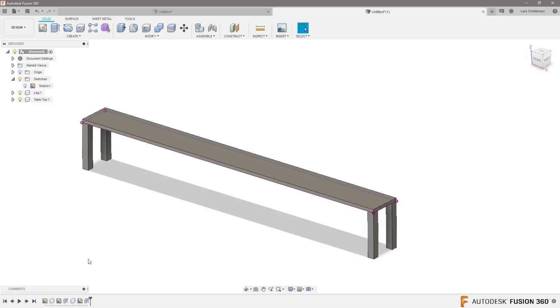But what I can do is hold down Control and select these 3, they all belong together. If I right click on them, you can create a group. And when you do that, they all get grouped together in here. You can hit the little plus sign, expand them, or hide them down like that. Same thing, I created these in an order. I created first the component, then the sketch and the extrusion. I can also select these 3 items, hold down Control, right click, and group those together. So that's one way that you can start ordering things together in this timeline.